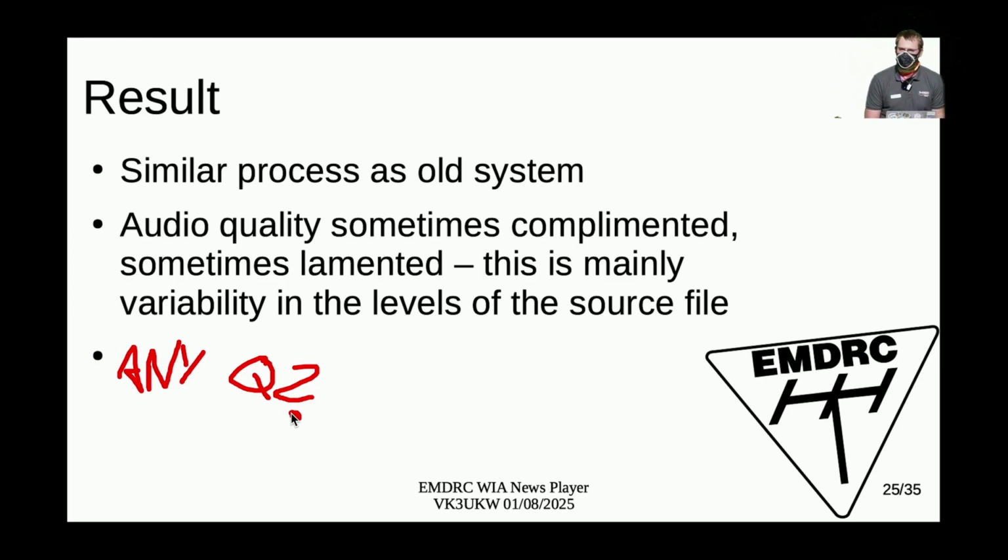If you've got a voice broadcast, the 30 decibels is 30 decibels below the peak level, right? So you've got me talking, and every time I stop talking, obviously the audio level goes down. Even if you've got background noise, background music, whatever, if I want to create an audio file that has my audible voice, me audibly talking, then whenever I stop talking, the audio level has to go down.